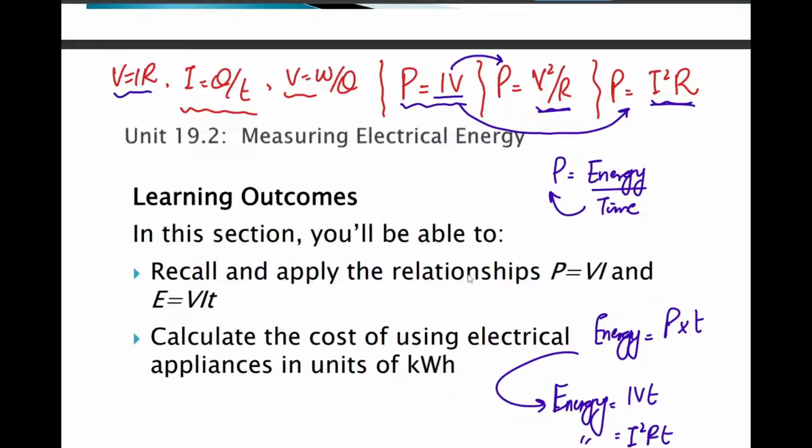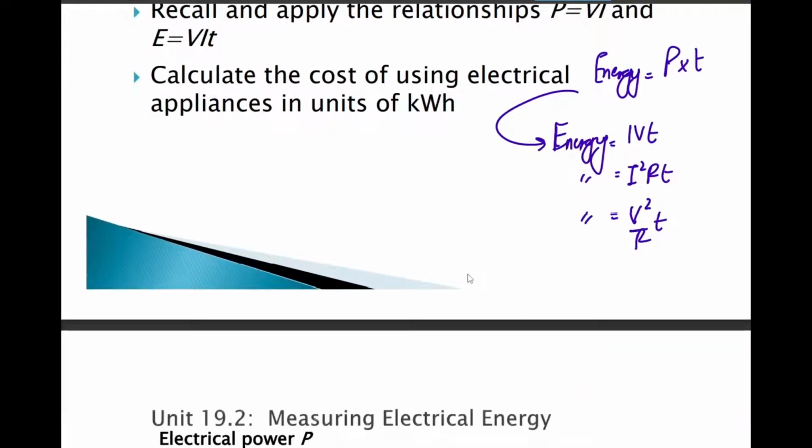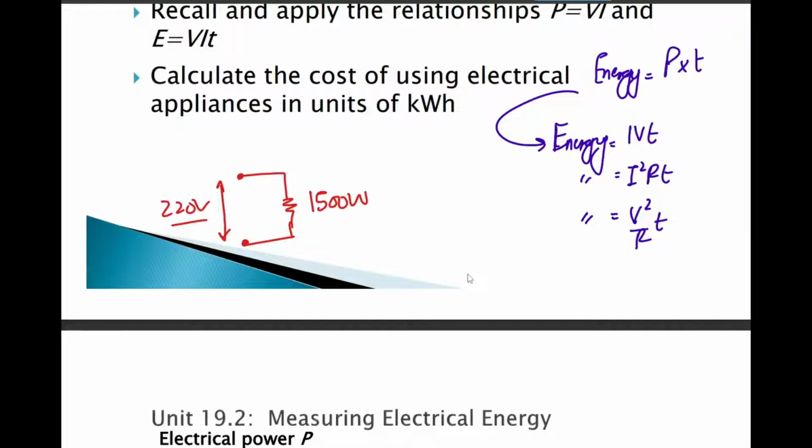Alright. So, for example, let's say this is an air conditioner. If I know that it takes in 1500 watts of power and operates on a voltage of 220 volts, here in Pakistan we have 220 volts, I can find out the current it would demand from the source by simply using the formula P equals IV.